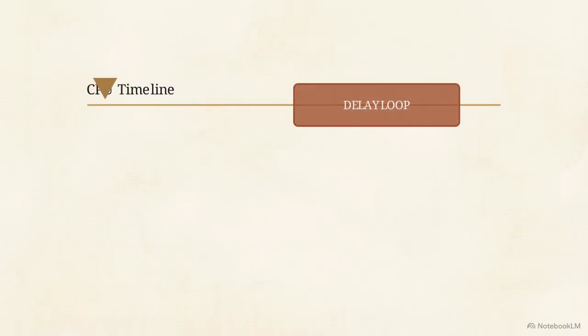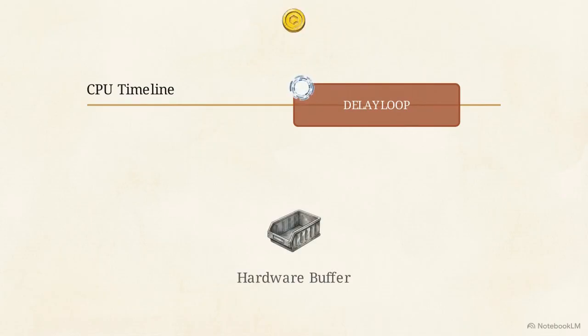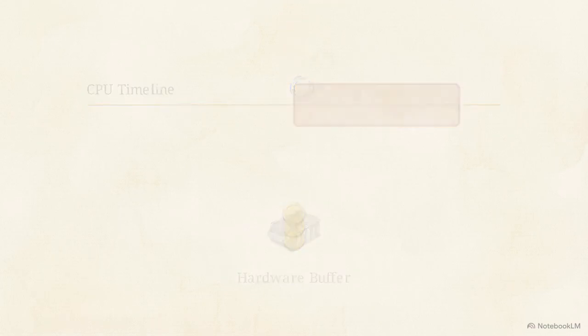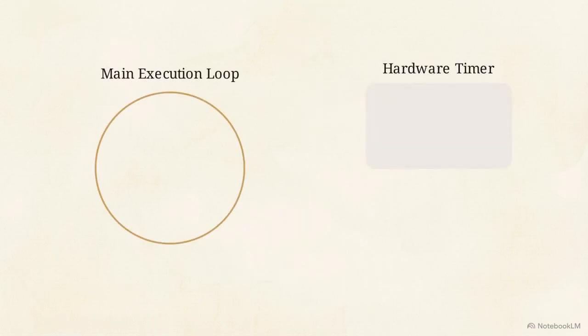This diagram illustrates why that method is a mind killer for a processor. The delay command forces the CPU to stop evaluating code and simply count clock cycles. During that countdown, the chip is completely deaf to the outside world. If a user sends a command during that pause, it piles up at the barrier and is entirely ignored.